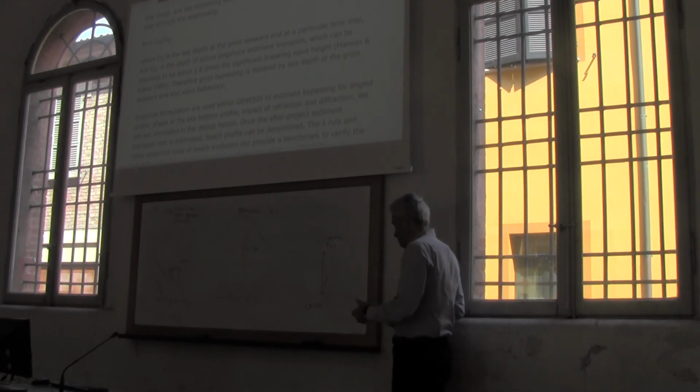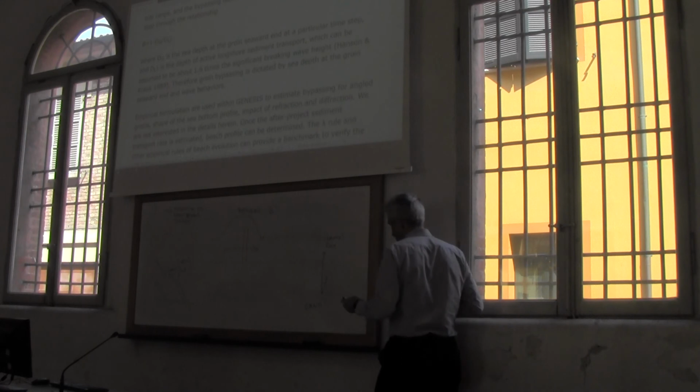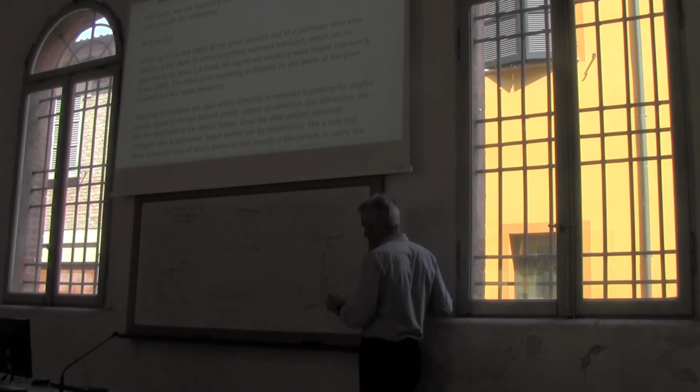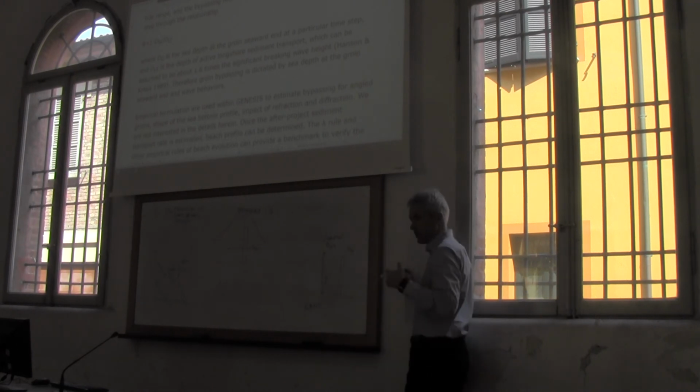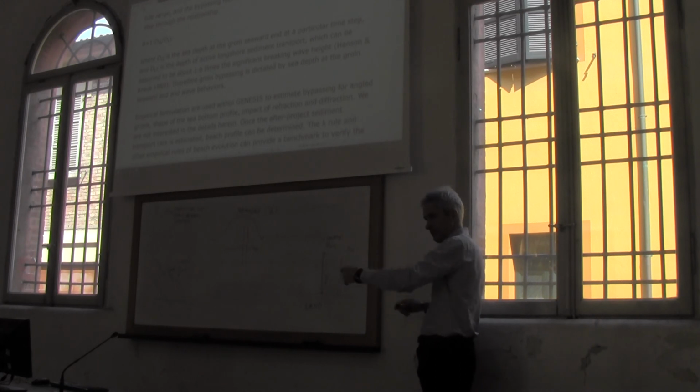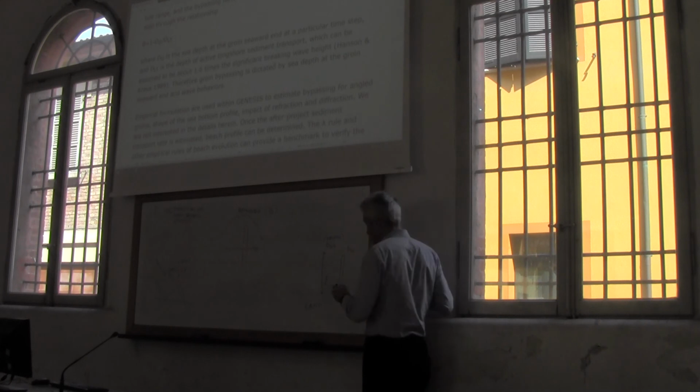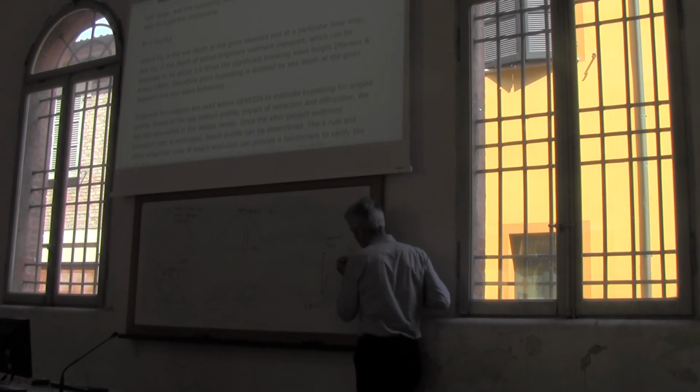Now let's suppose that I build a groin, and let me assume that it is extended up to the active sediment transport. In any case, I build a groin and I indicate with DG the depth of the groin at its offshore end, which is of course related to the length of the groin, LG.